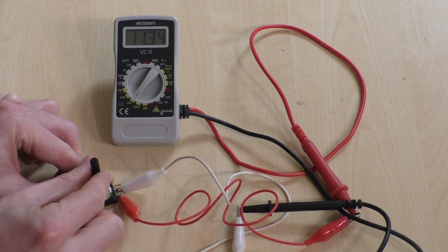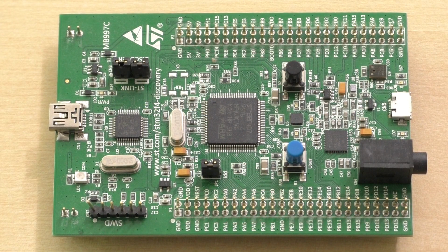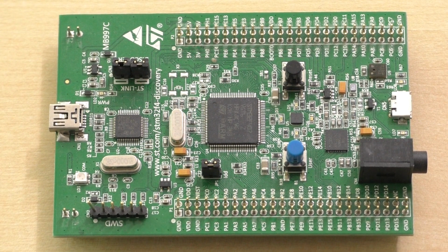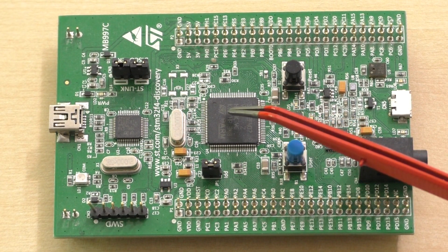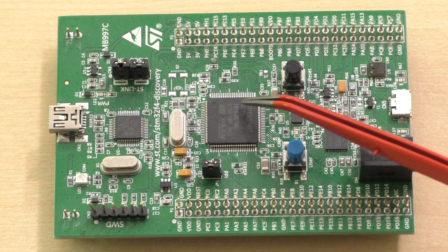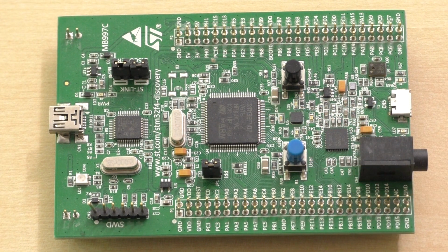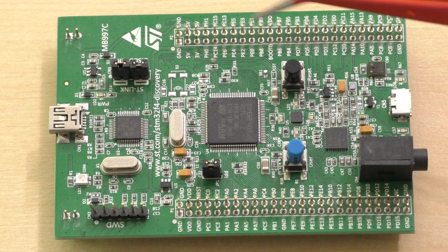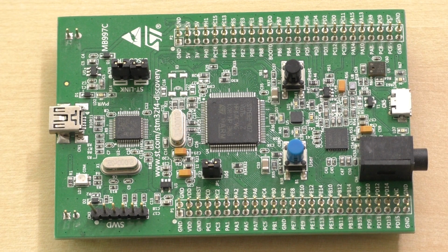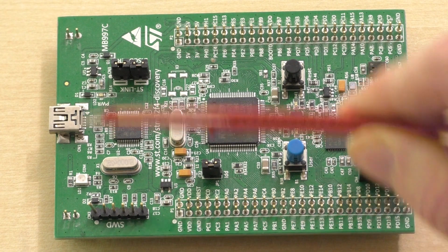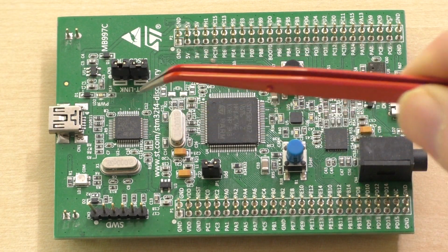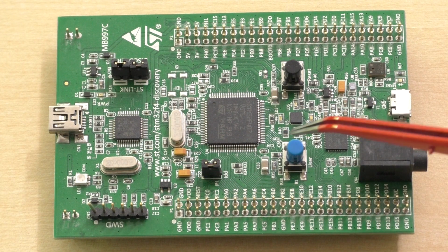In my case, I use an ARM Cortex M4 microcontroller to handle the AD conversion and transmit the resulting numbers to my PC via a USB connection. The microcontroller itself is just this small chip here. The input-output pins of the controller are connected to these pins on the side of this STM32 discovery board that is made to simplify development and debugging for this microcontroller. There is a lot of other stuff on here as well, such as USB plugs, a programmer and debugger, quads, buttons, LEDs, a microphone, and so on.